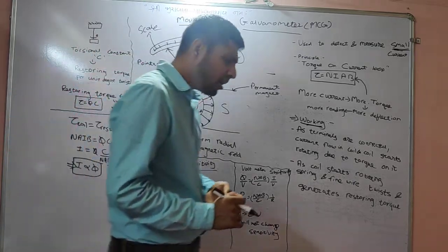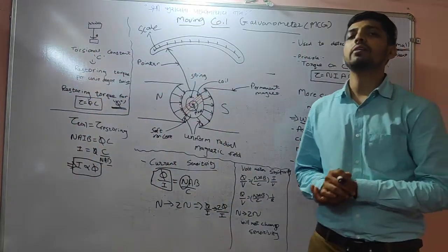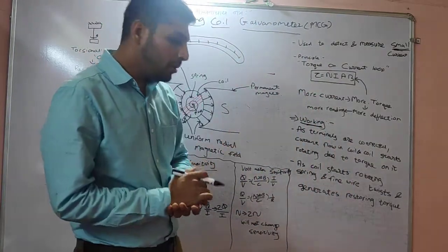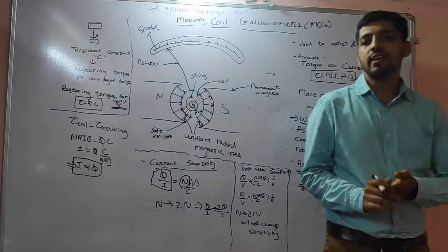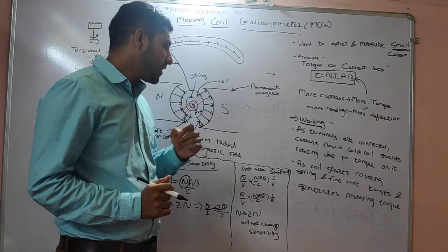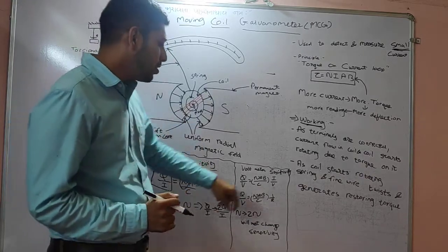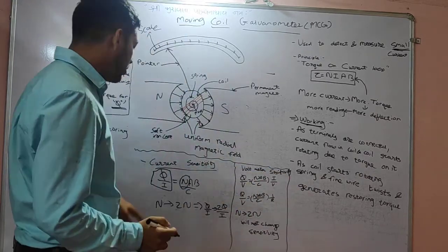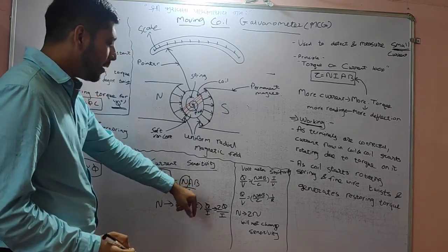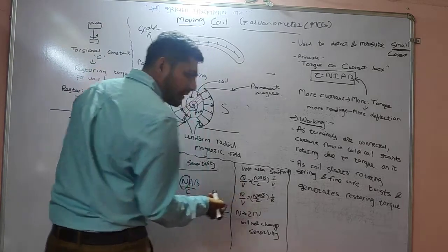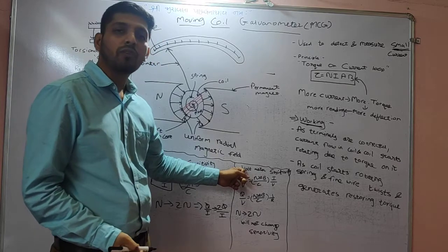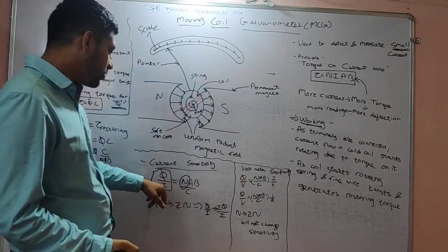Now from this galvanometer you can also make a voltmeter and an ammeter, but we will not be talking about that in this lecture. We will just talk about, if it is converted to a voltmeter, how we can check the sensitivity of the voltmeter. So for voltmeter sensitivity, I have just rearranged this term, phi by I equals NAB upon C. Instead of that, I have written phi by V. If this is the sensitivity for current, then this will be the sensitivity for voltage.